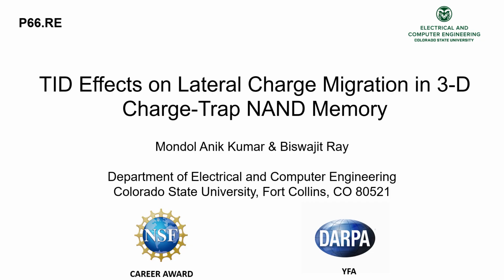Today, I'll present our work on total ionizing dose effects on lateral charge migration in 3D charge trap NAND memory. In this study, we investigate how gamma radiation influences threshold voltage dynamics, both during irradiation and in the post-irradiation retention phase.